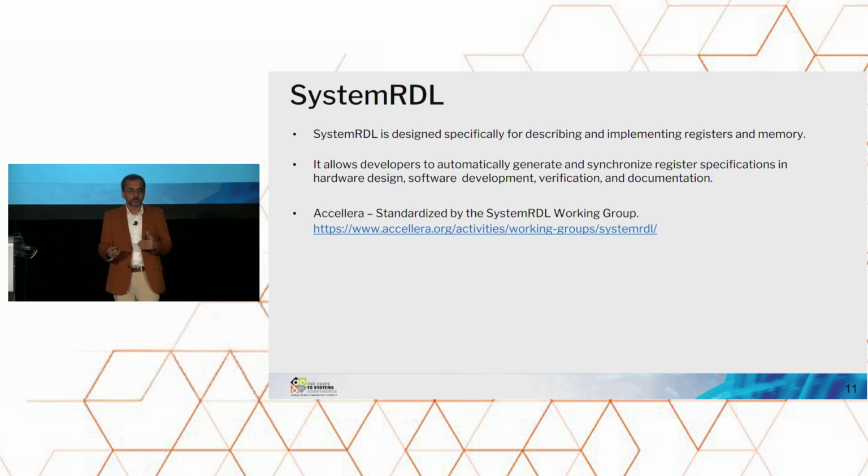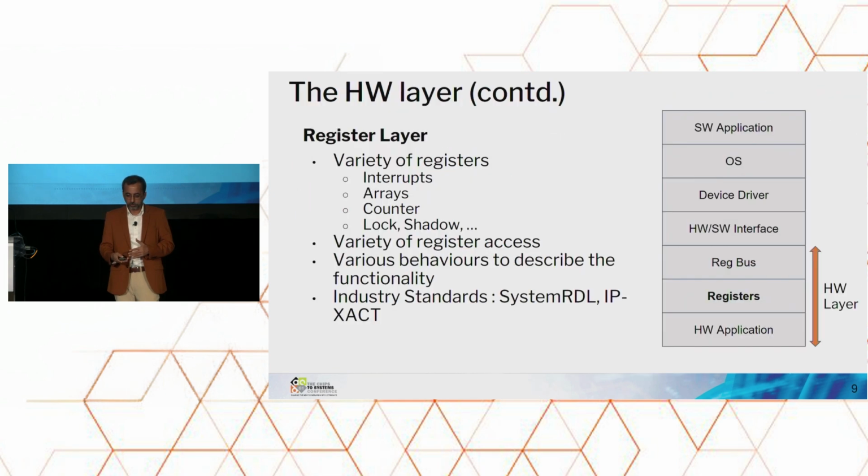That language is used to describe these registers and memory and the register map and all the attributes and behavior, not necessarily too much about the behavior, but all the attributes about it. But you can extend it with UDPs and add behavior to it. For example, some of the register types I showed, like interrupts and counters, are intrinsically part of System RDL, but for others, you can add UDPs, user-defined properties, and you can add additional behavior to them.